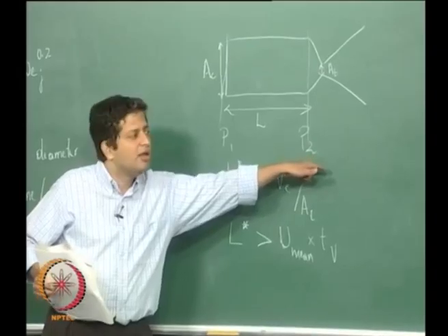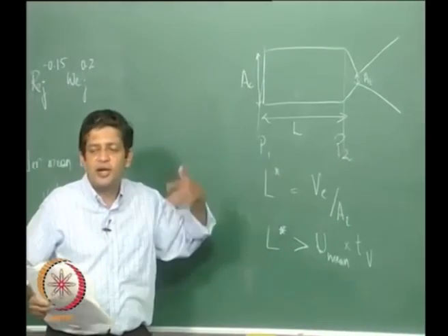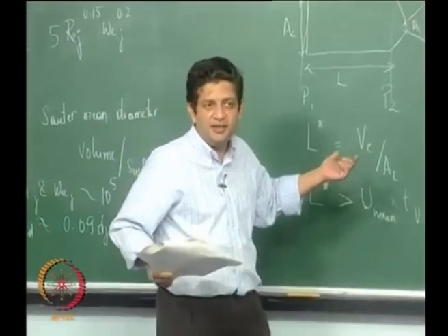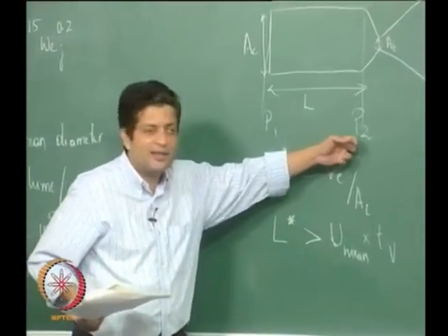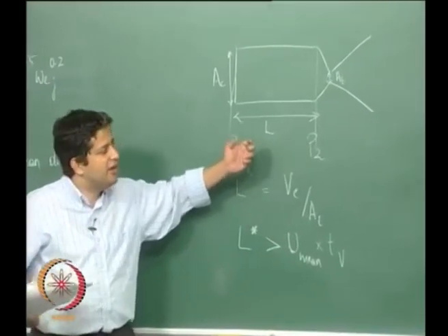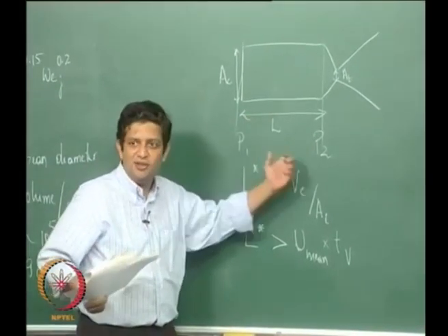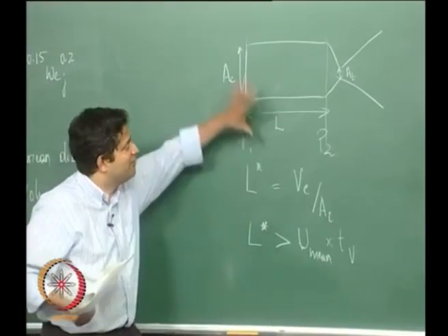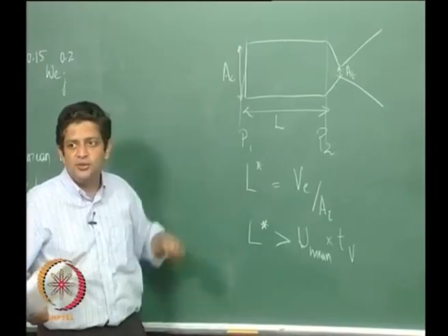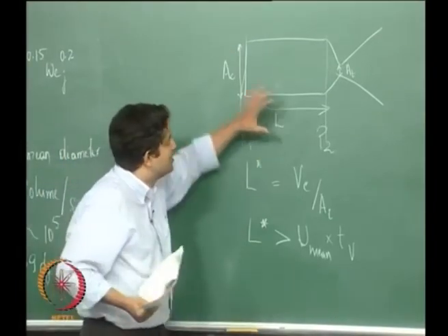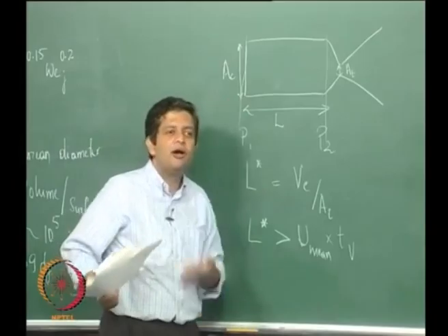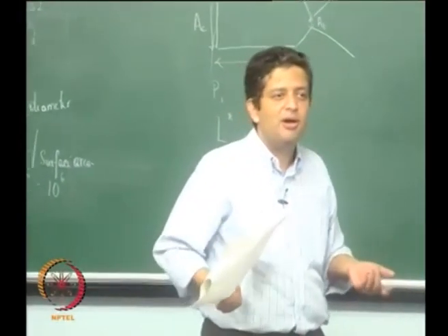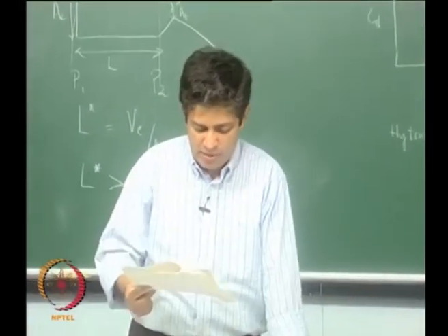If you look at the thrust equation, PC AT CF, this is the one that governs this. So we need to ensure that the pressure drop from the head end to the nozzle end is as small as possible, right. So then this sizing needs to be also done. Primarily this AC is determined on how many injectors and how do we house them. That is the one that drives how we choose AC, okay.